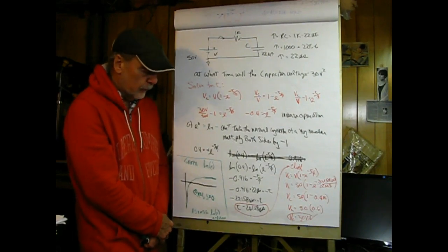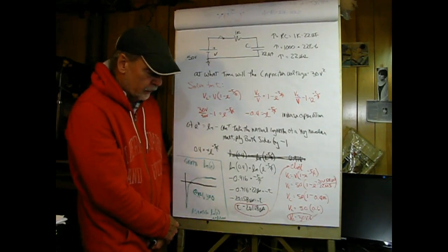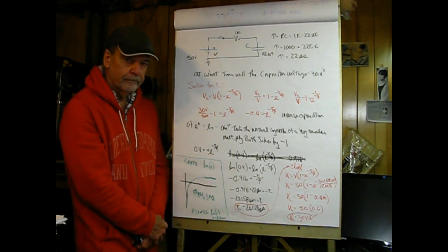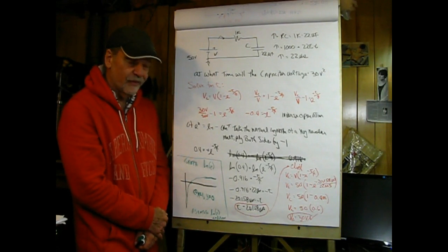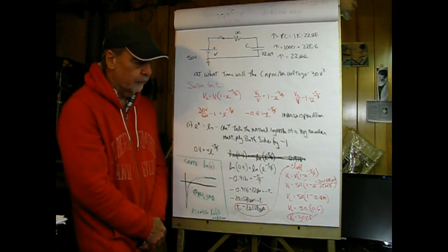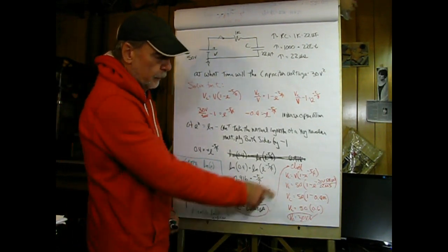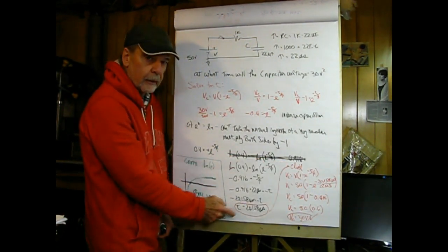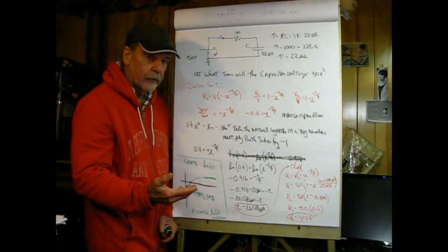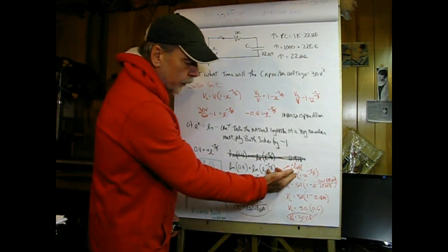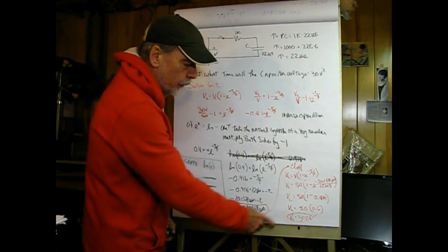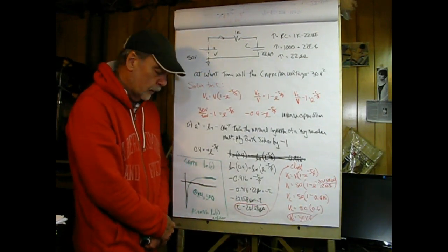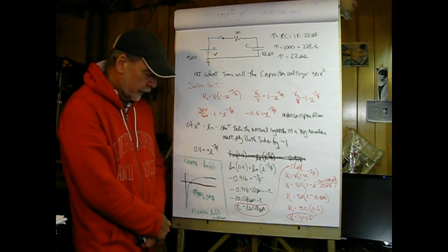Again, multiplying through by negative 1 gives us a time of 20.158 microseconds. Now, that's nice. Is it correct? Well, I don't know. Let's check it. So what we'll do is simply put in our values here, and for t we're going to use our solution, and what we should come out with, hopefully, is 30 volts. In working through this, just like we did before, we end up with VC equals 30 volts, so I'm fairly confident that the solution is correct.